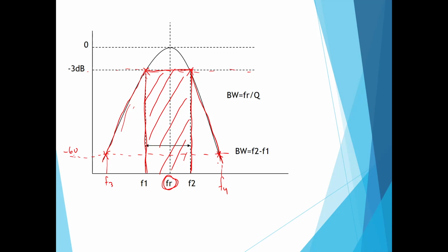But when we want to design the filter, we want to design a filter that has a very steep slope. The steeper the slope, the better, so that we can remove the unwanted frequencies, because we don't want any frequency over here. We just want the middle here, ideally.